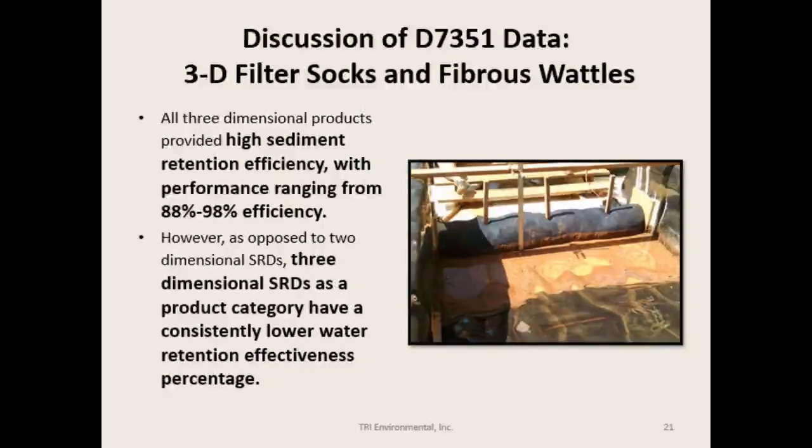All three-dimensional products provided high sediment retention efficiencies with performance ranging from 88 to 98%. However, as opposed to two-dimensional SRDs, three-dimensional SRDs have a consistently high flow rate. But caution is in order. As discussed previously, the low profile of three-dimensional SRDs can lead to a requirement of more frequent maintenance to maintain product performance.